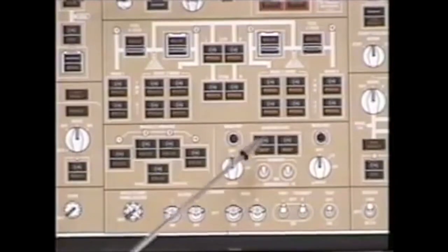Window heat will turn on the window heat left and right. These switches control window heat to the number 1 windows only, L1 and R1, for strength and anti-ice purposes. Windows 2 and 3 are heated with low voltage only for defogging purposes whenever there's power on the airplane.